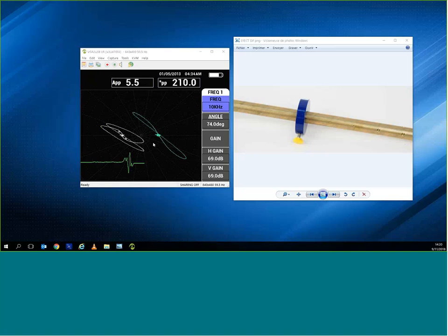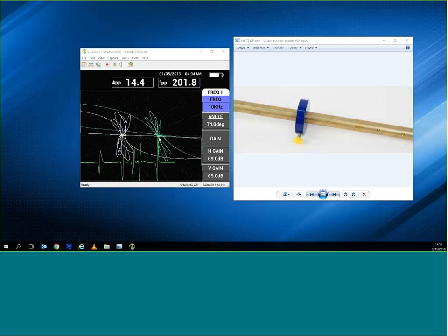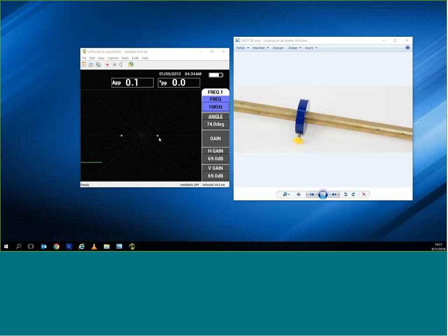So what is interesting to see here is how on frequency 1, you mostly see a support signal. Frequency 2, you kind of see it too, but on the mix, you just see the hole. So using the auto mix function, it's really easy to find defects under supports. And I'll just scan the entire tube with all the remaining defects. So there's our defect, another one, and we have an ID right here. So that's for eddy current differential. Very crisp signal, very fast scanning speeds, very simple to use.